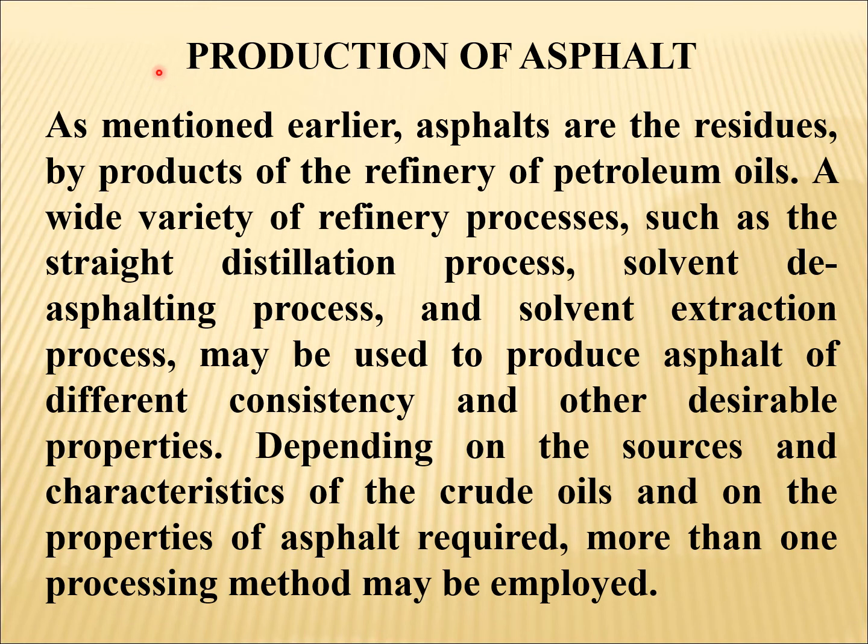Production of asphalt. As mentioned earlier, asphalts are the residues, byproducts of the refinery of petroleum oils. A wide variety of refinery processes such as straight distillation process, solvent de-asphalting process, and solvent extraction process may be used to produce asphalt of different consistency and other desirable properties. Depending on the sources and characteristics of the crude oils and on the properties of asphalt required, more than one processing method may be employed.